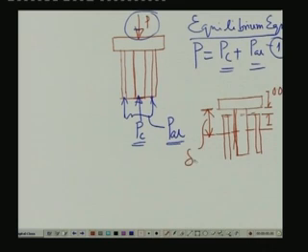This we call as delta C, and in the process when the copper rod deforms to this extent, and if this is the position where the bearing plate has come, then the deformation which has occurred in the aluminum is this much. This we call as delta aluminum. So, from this particular configuration we can write delta C is equal to delta aluminum plus 0.05 millimeter.